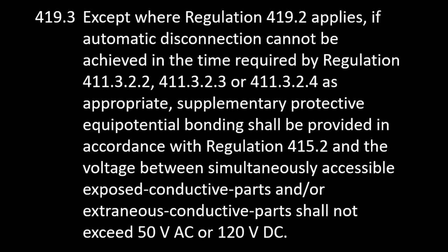And I've seen this most commonly done in intake rooms, in areas where we've got a large plant. The incoming supply is fairly large, which means our protective device is so large that we can perhaps not achieve the 5 seconds, but we will eventually disconnect. But all our outgoing circuits from that intake room have got a much smaller protective device, so they're fine. It's just that incoming supply cable that gives us the concern.